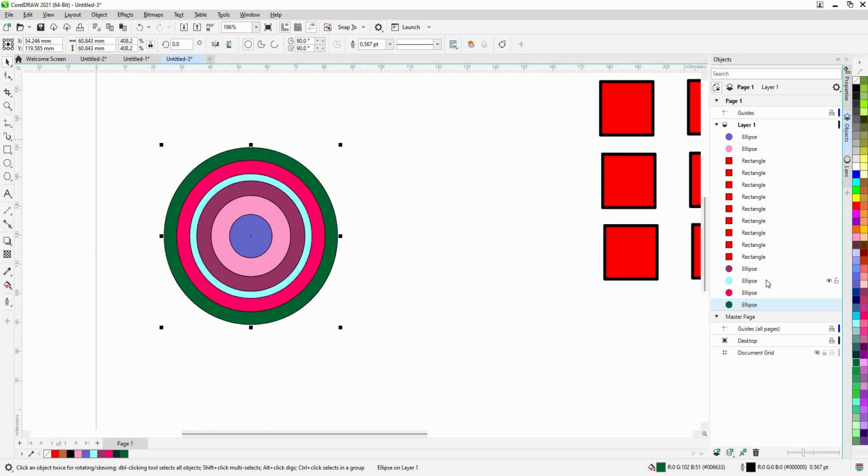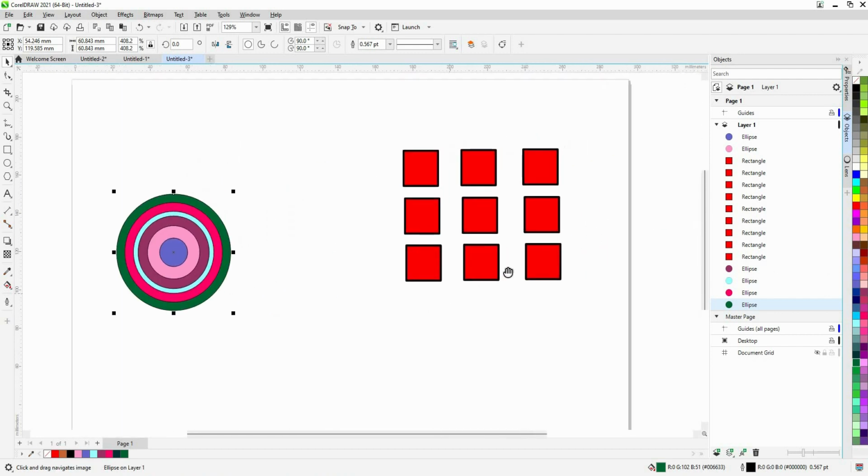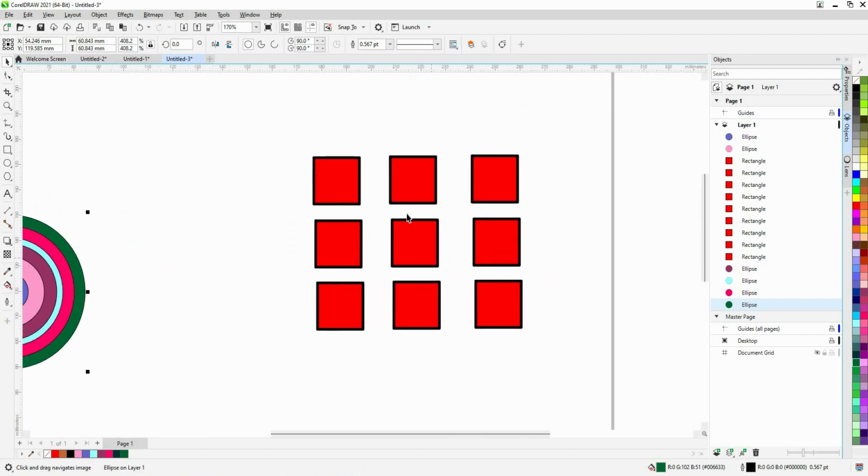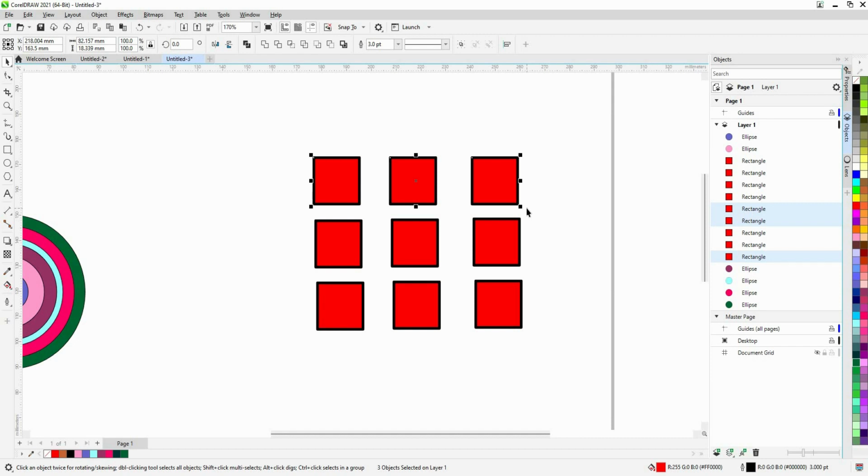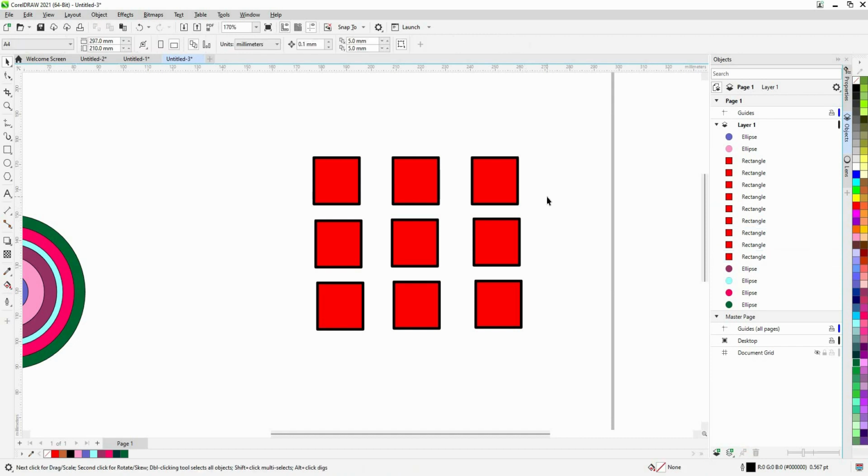So we also have some other alignment commands. Say I'm going to select these elements here, select this, I'm going to press T for the top and Shift E for even, and those will align them evenly, spacing them evenly.